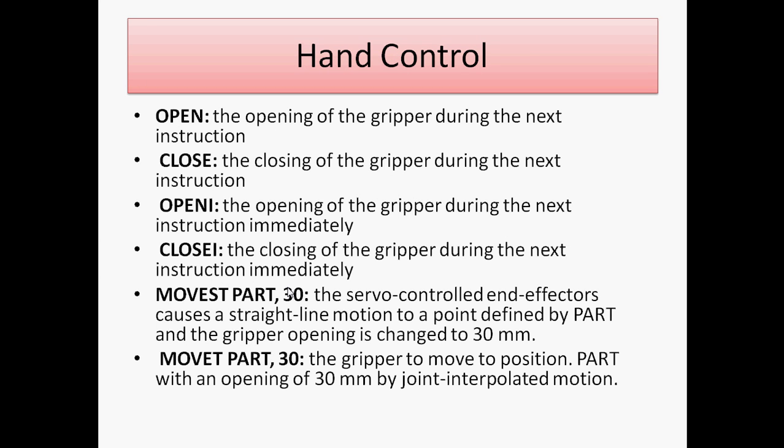Next we have the hand control. The command OPEN opens the gripper during the next instruction. CLOSE closes the gripper during the next instruction. Then OPENI opens immediately. Secondly, CLOSEI closes the gripper immediately. So we have the closing of the gripper side, that is CLOSEI. The function is the same between OPENI and CLOSEI.